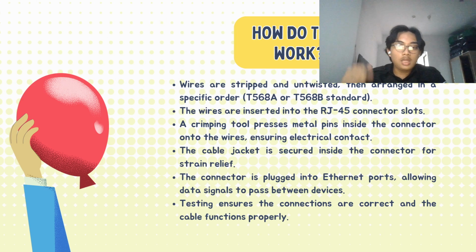And then the cable jacket is secured inside the connector for strain relief. The connector is then plugged into the Ethernet ports, allowing data signals to pass between devices, and then testing ensures the connection is correct and the cable functions properly.